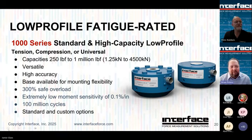So instead of the typical 150%, you're going to get 300%. And as mentioned earlier, very low off-axis sensitivity, actually guaranteed to be less than 0.1% per inch, and 100 million fully reverse cycles. And of course, many different options, whether it's multiple bridges, different connector types, connector protectors, TEDs, you name it, we can offer it on these. Next slide.